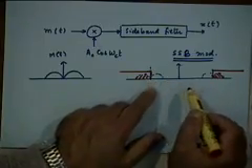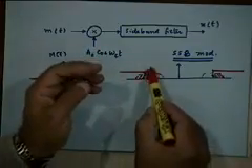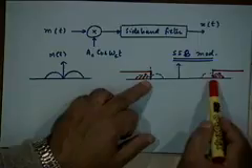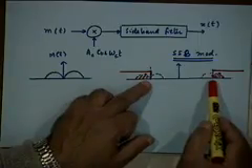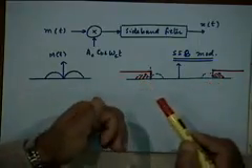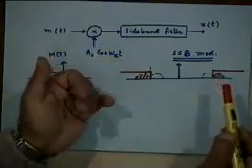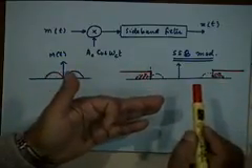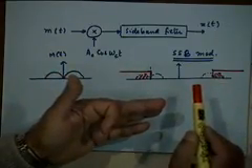If you want the lower sideband, you should have a low pass filter with a cutoff frequency of fc, right? So depending on whether you want the lower sideband or the upper sideband, you can use an appropriate filter, which ideally could be either high pass or low pass. Is it clear?